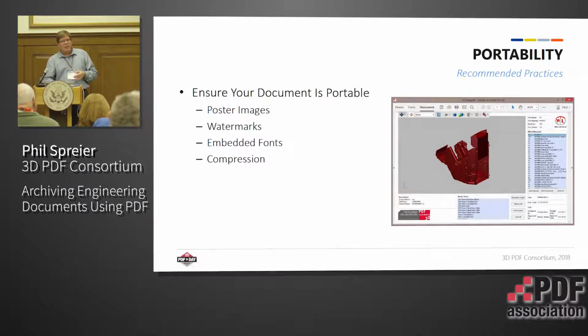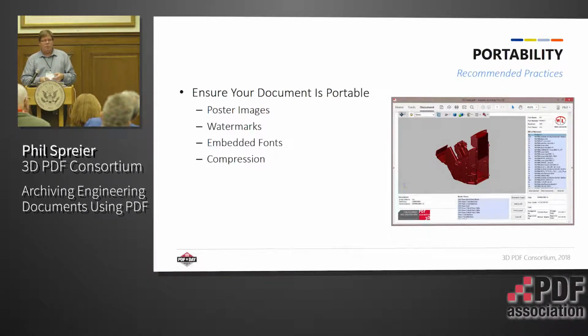The one that I'd like to really emphasize is fonts, because fonts are very important. In the CAD world, we use a lot of different fonts, mostly for dimensions and tolerances. Oddly enough, your standard Times Roman does not have a perpendicular tolerance symbol in it, right? But there are some that do, and Adobe came out with one called Myriad CAD, and it ships with all the Adobe products.